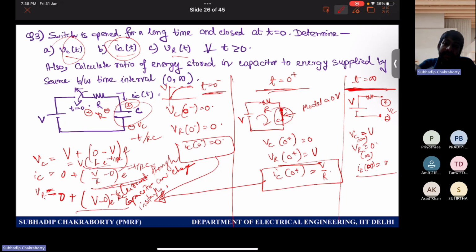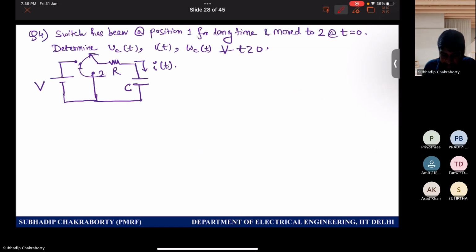It should, because the capacitor voltage is rising, and to maintain the KVL loop, it is reducing its voltage, which is natural because the current through the circuit is reducing because of the capacitor charging itself, and hence the voltage drop across the resistor is also reducing with time. So accordingly, it is coming, right? I hope this was a very easy problem, right?